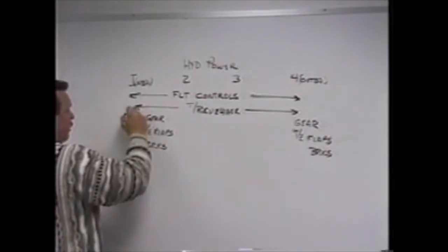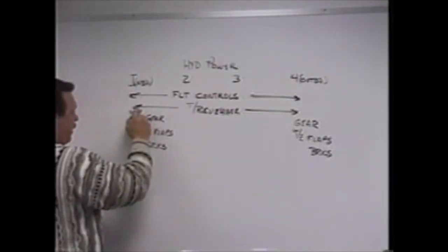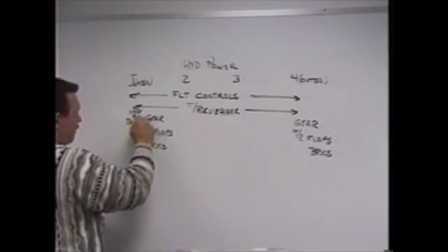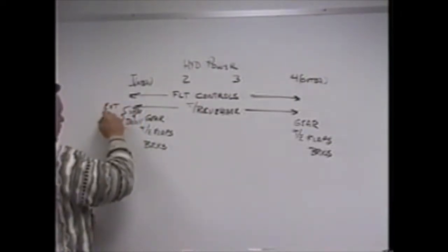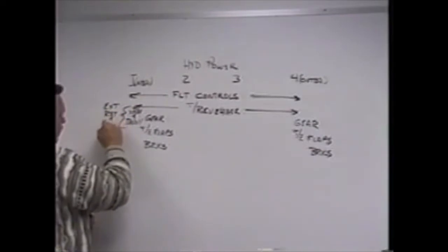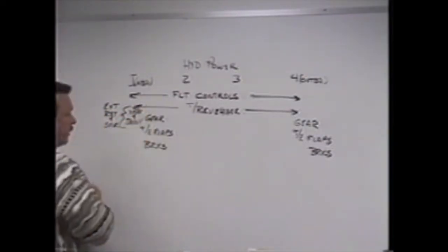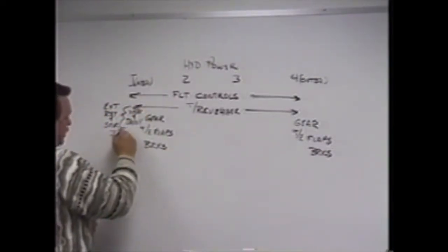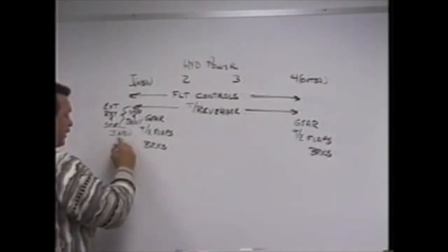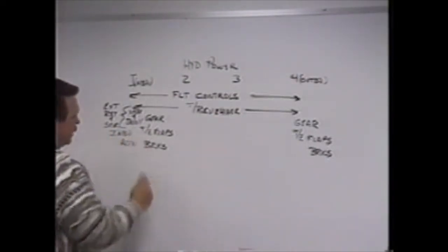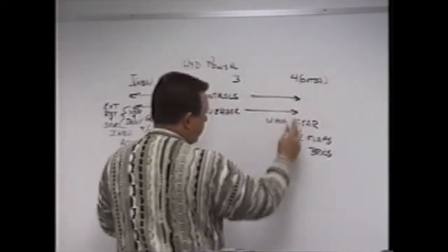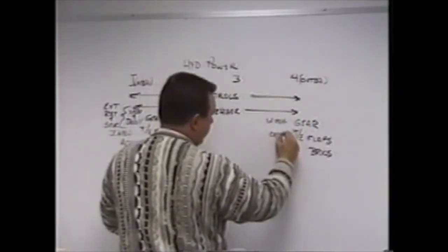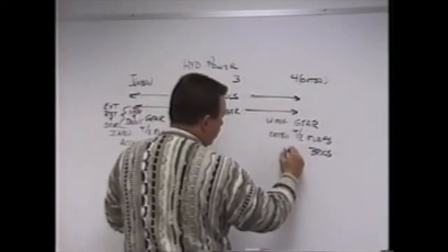Inboard gear, that would be the nose and body gear. You're talking the normal extension, retraction, and steering for both the nose and body gear. Inboard trailing edge flaps and alternate brake system. Outboard gear, that's called the wing gear, outboard trailing edge flaps, and normal brake system.